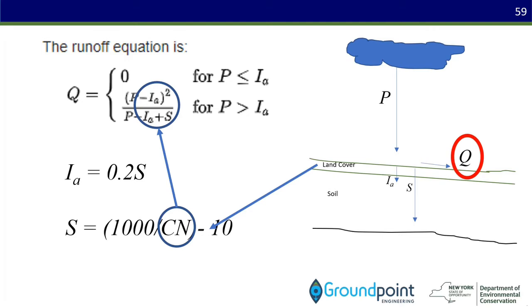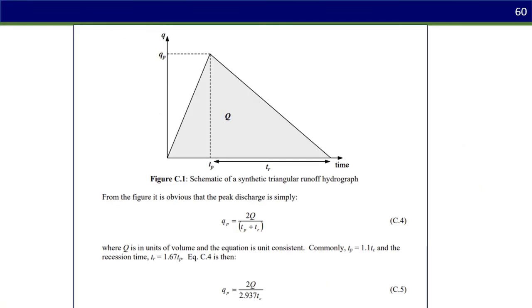So we need a way to translate this volume of water that came out of the sky and is moving across the landscape into a peak flow based on the characteristics of the watershed. That requires our elevation model to calculate slope, distance, and travel time. That way we understand what the rainfall has to do before it arrives at the front end of our culvert. So here's a super simplistic way to look at that.